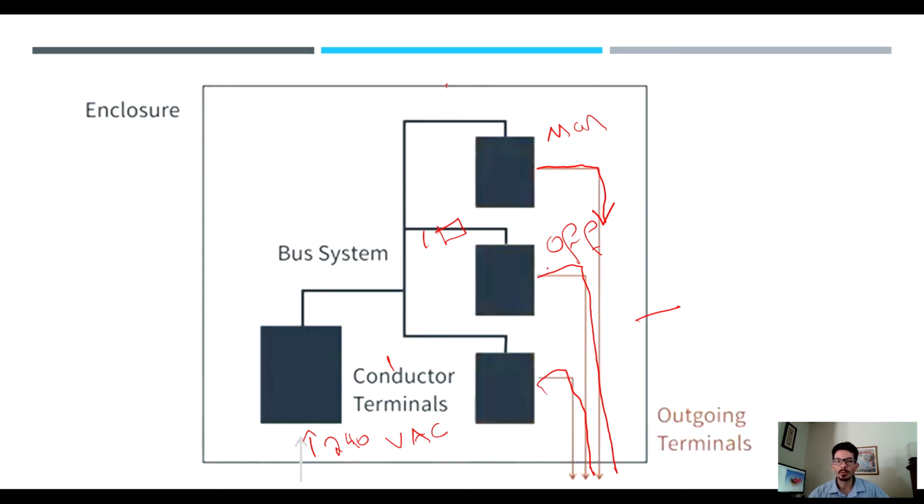So that would be pretty hard to service if you combine, which happens, and it's sadly not very useful because this is one reason why there are so many accidents, because people don't follow standards in many cases, where they have the same control panel for everything, where they need to within the control panel organize their loads in different sections.